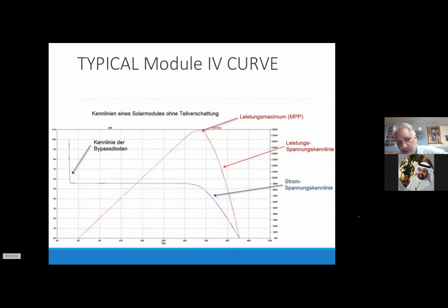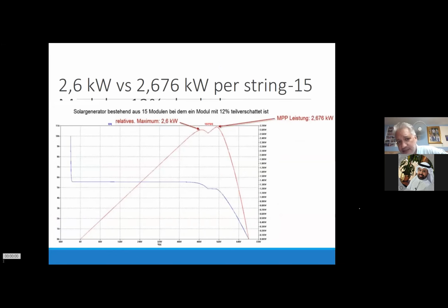That's the typical IV curves. If you measure, in the old days with 15 modules and different maxima, which global or local maximum the inverter will try to see. Danfoss, for example, had a sweep configuration. So every half an hour or 1 hour, you could set that point. It actually went through the whole spectrum. Normally, it stays within 5%.